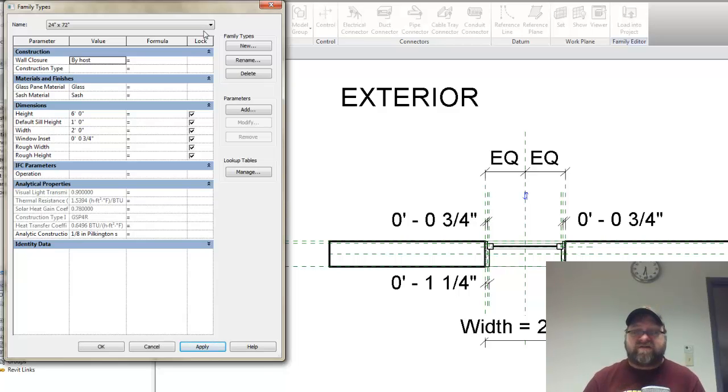As part of the last note here, when we're making the family, we have to make sure that we don't create constraints that are going to compete with one another. You can over constrain something so geometry can't get produced, so this flexing process is something we can use to guard against creating an over constrained model. So I think that's a basic introduction to the whole idea of creating new components, or creating something that wasn't made before, building it in the family editor and then using it in your project.